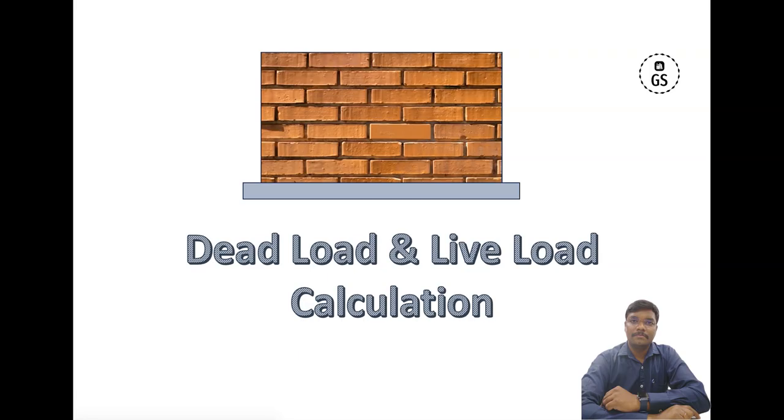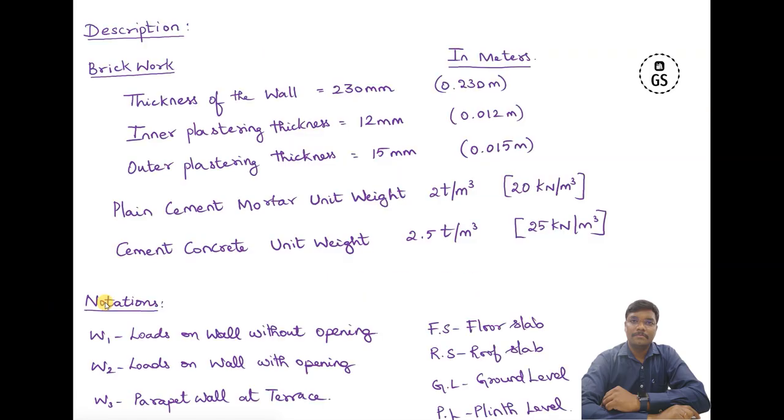Before that, we should know some basic things, how to calculate the dead loads with basic parameters. These are some descriptions I have taken for my calculations. The thickness of wall is taken as 230 mm, and inner plastering we do for walls, that is 12 mm I have taken, and outer plastering is taken as 15 mm. And we should also know that the plain cement mortar unit weight is 20 kN/m³, and cement concrete unit weight is 25 kN/m³.